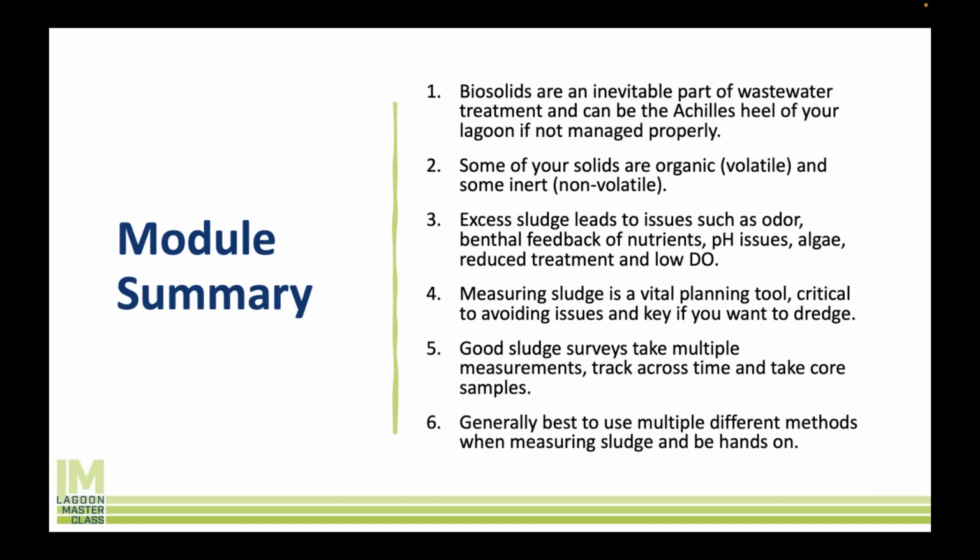Measuring sludge is a vital tool. That's how you guard against those issues. You've got to understand how much sludge is in your lagoon. Good sludge surveys are all about multiple measurement points, tracking across time, taking core samples, and understanding the volatile versus non-volatile component of your sludge.